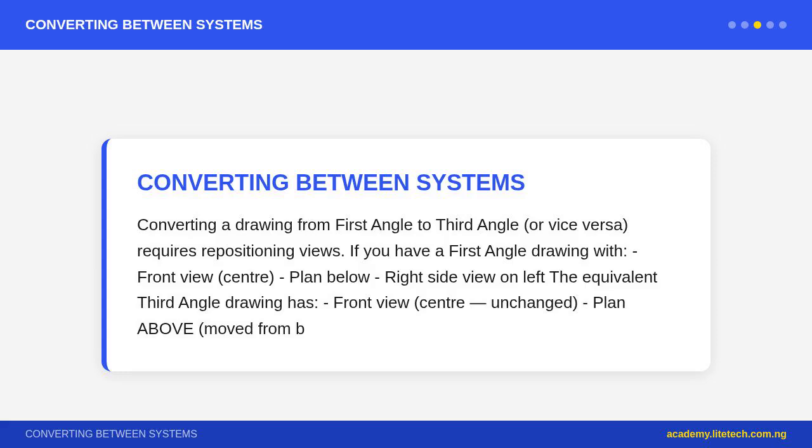Right side view, to the right of front view, rectangle 40 by 30 mm with a step visible in the top right corner of this view, shows the 15 mm height of the step and the 40 mm width is the depth. All 3 views together completely describe the step block, dimensions, positions, and the notch feature.